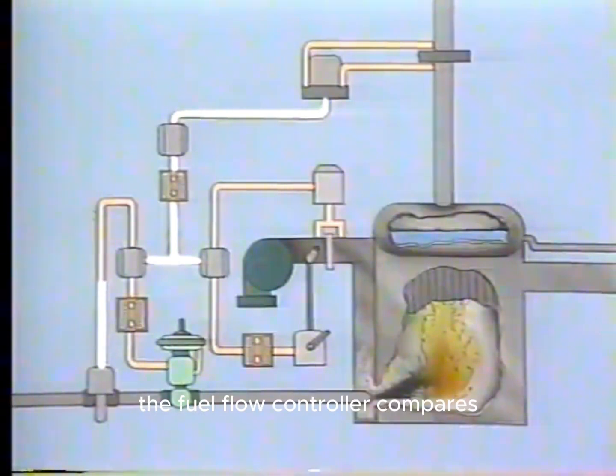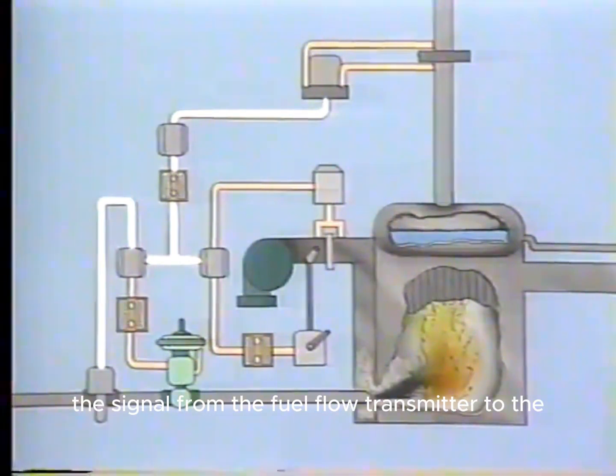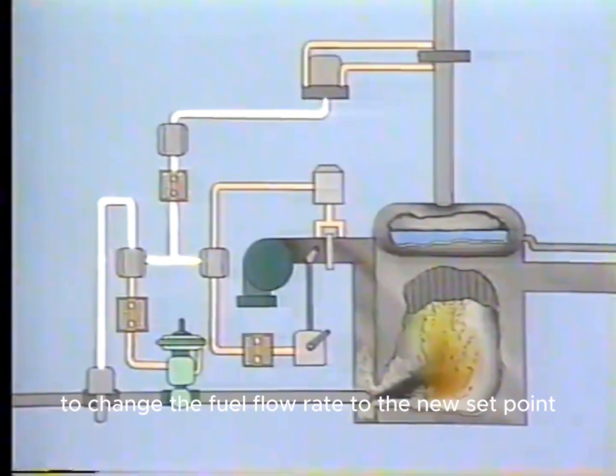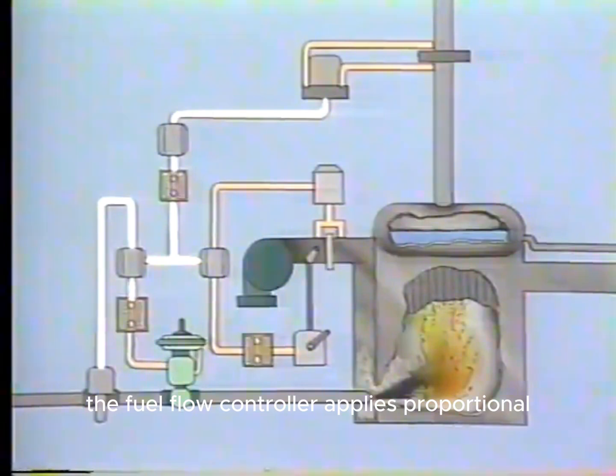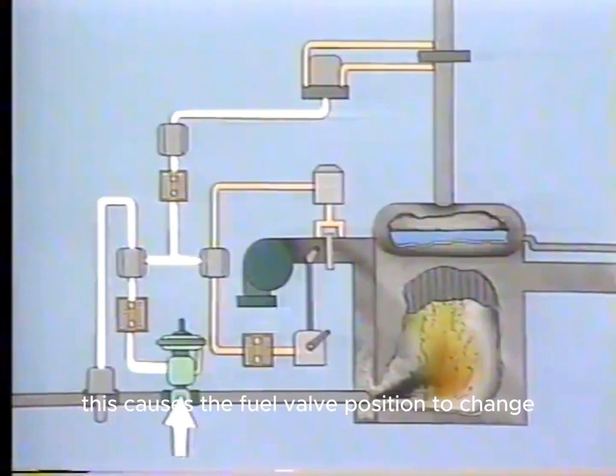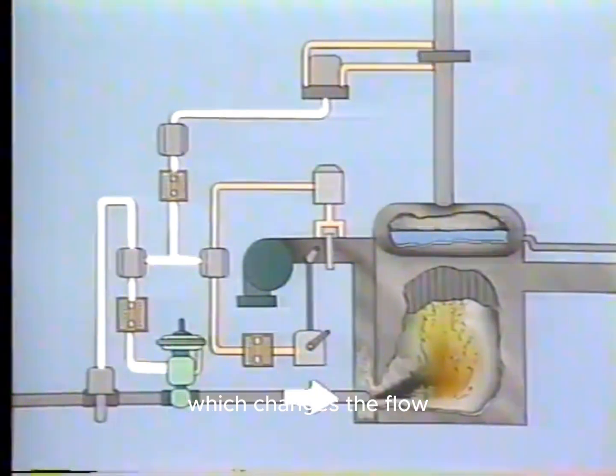The fuel flow controller compares the signal from the fuel flow transmitter to the new set point. To change the fuel flow rate to the new set point, the fuel flow controller applies proportional plus integral action to the final control element. This causes the fuel valve position to change, which changes the flow.